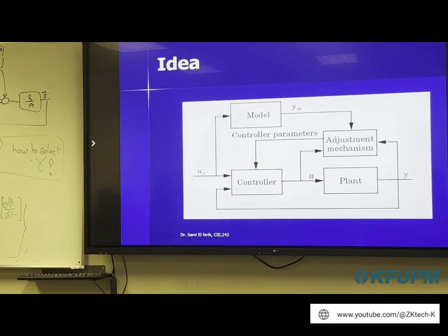So if we have a control system running on some microcontroller or microprocessor, basically we will have to run two loops, one for the current controls and the other for the system identification. Why not do identification right now? No identification. It will just find the parameters for the controller, and if a new update is available, then it will change the controller. Otherwise, the one loop continues all the time.